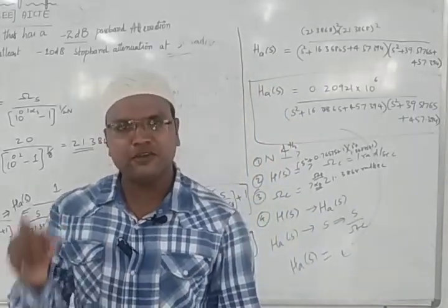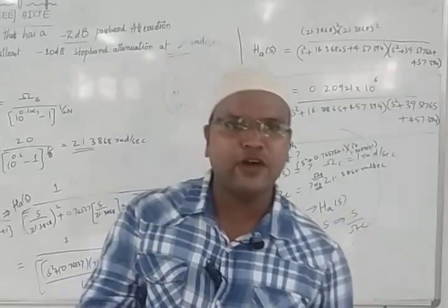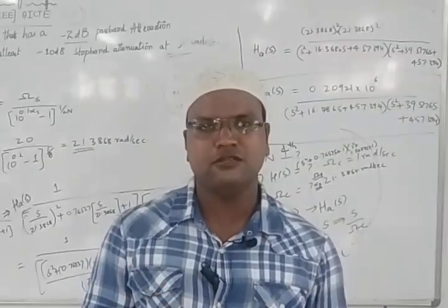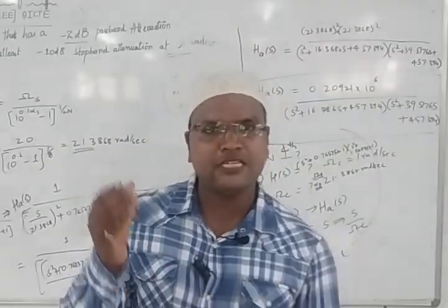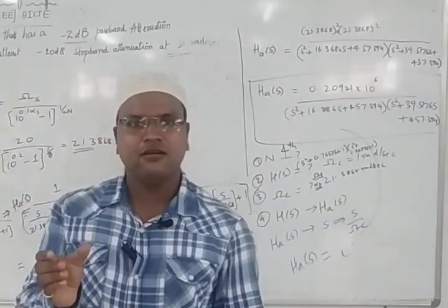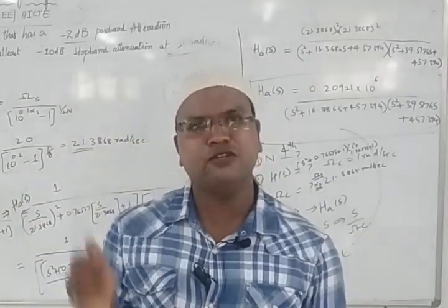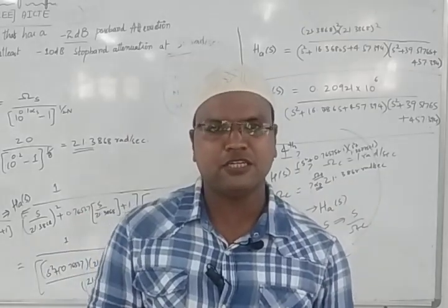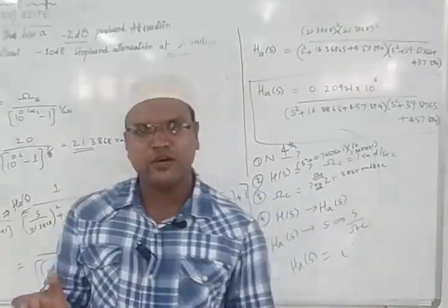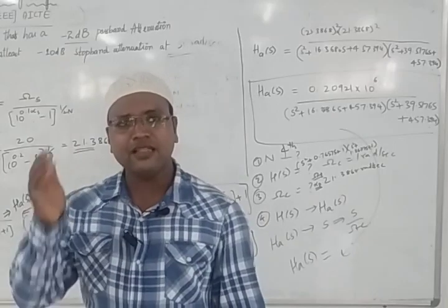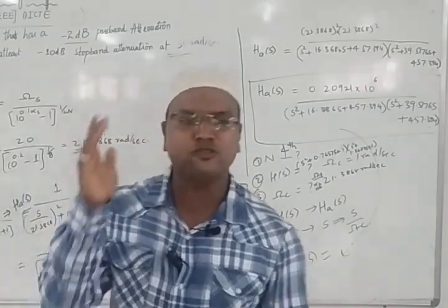As soon as we are done with the order of the filter, we have to find the transfer function. So how do we get the transfer function? By taking the value of n. If n is the first order, we have a denominator polynomial with constant values. N equals 1 means s plus 1. That means the power of s needs to be 1.